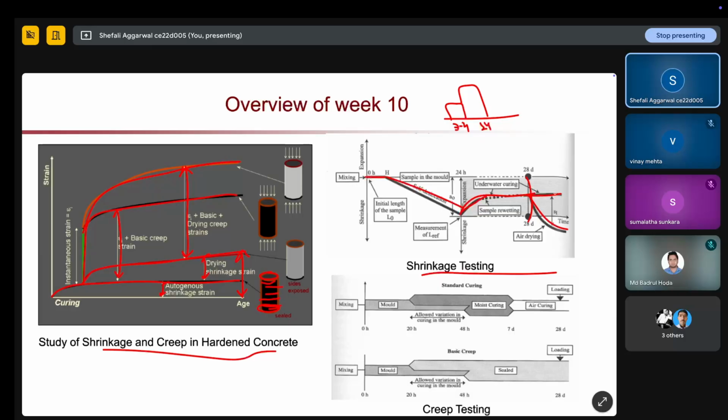and then there is an increase in volume, and then afterward, after 28 days curing, you will have your drying shrinkage, and again your other two types of shrinkage will follow up. Carbonation is a long term process, so it will be the least, and the volume change will also be almost very low.